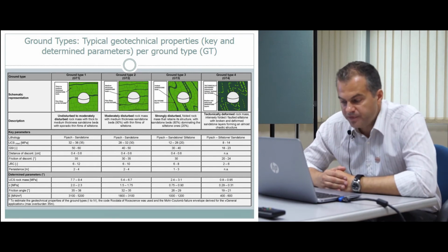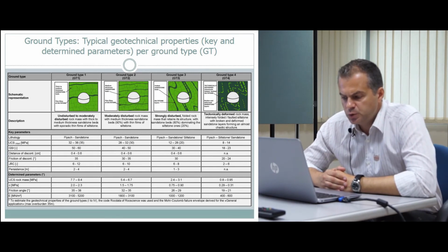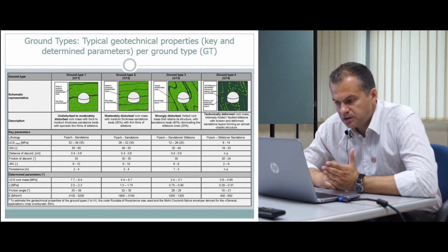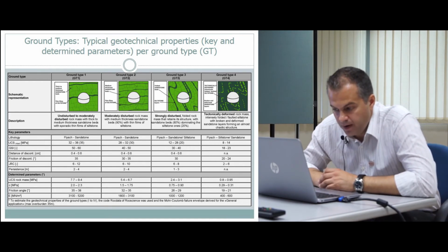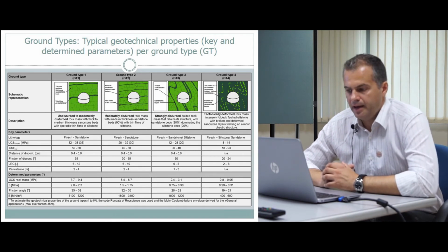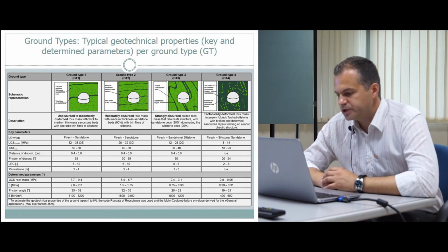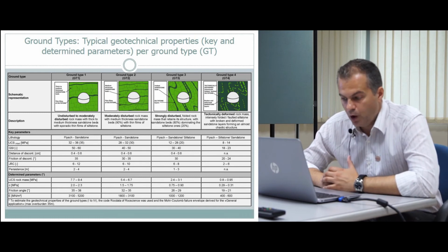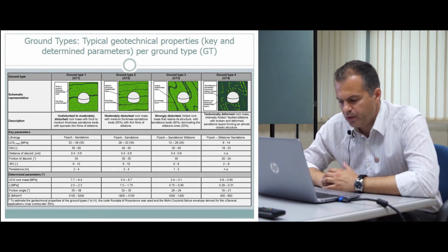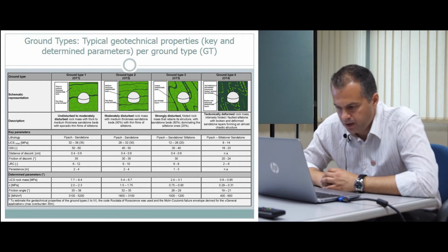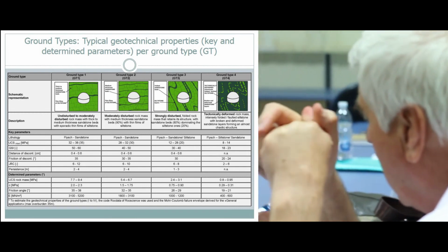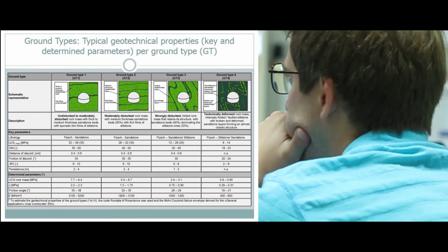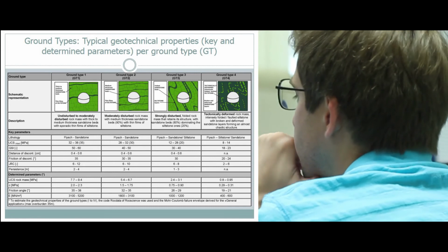In ground type 3, due to a wide range of the UCS, we may lie in the case of 13 or 14, which is a chimney type with wedge failures. If we have some low UCS there, we may also have some small shear failures along the tunnel perimeter, but mainly the problem is dictated by crown failure, so chimney type overbreaks and some wedge problems.